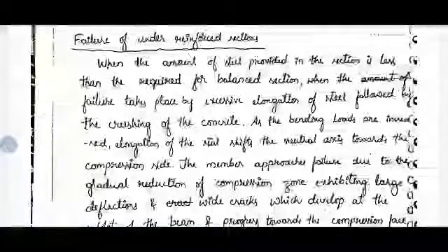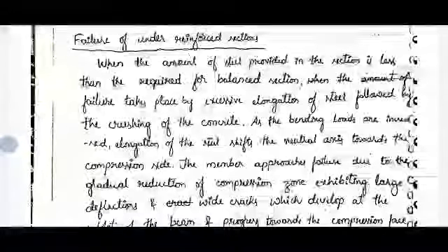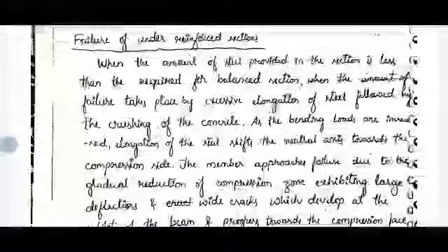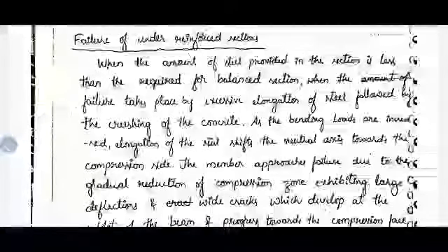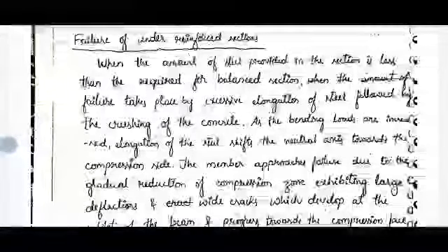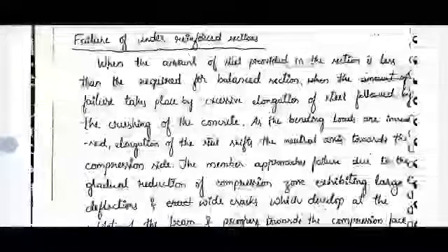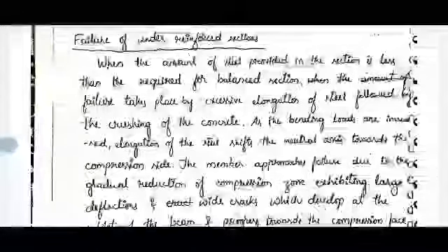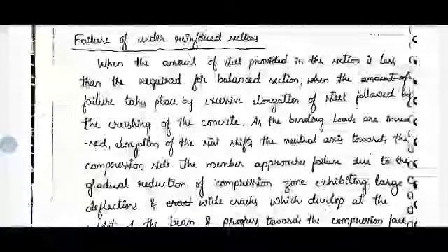So here, A_st minimum, we know there is a guideline for minimum steel. That minimum steel is the percentage of steel required for a balanced section. As discussed in the previous module, we have 0.2%. It is the minimum steel we need to provide for any section. But as per the analysis, the loads coming over it are enough for less than 0.2%.